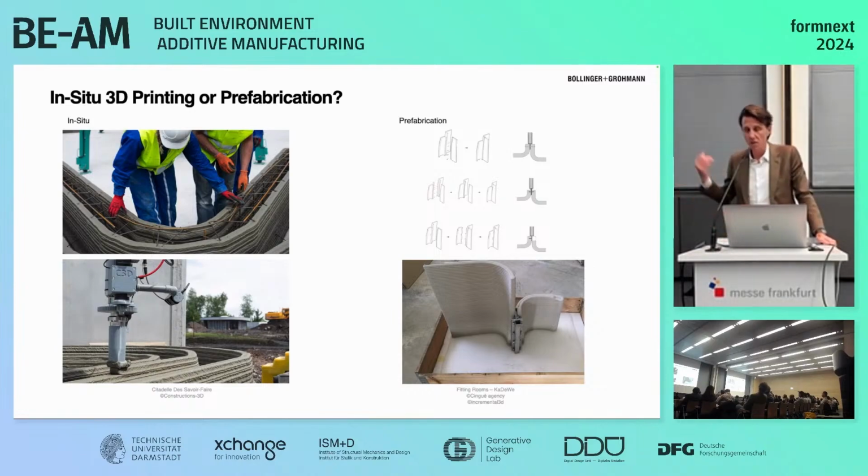And actually with this one, it was quite easy because it's actually Sika that gave a minimal value, which is, no, I shouldn't use that word, but actually they can go up much higher because they only give you 30 MPa or something, or 25. You could go up easily to 80. And with Lafarge, it's even the same. So they have the very high yield, but actually they give you low value to be okay with the regulations. Thank you.